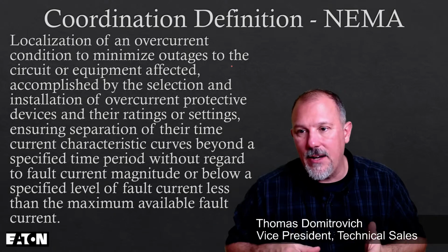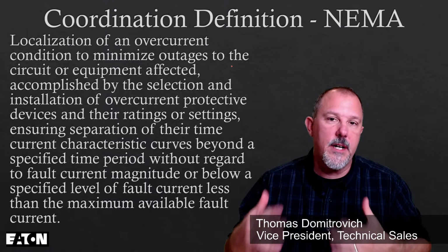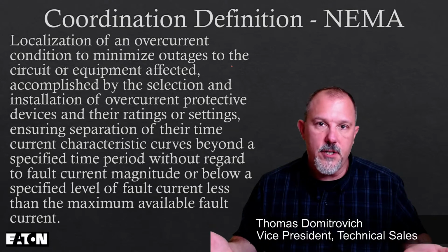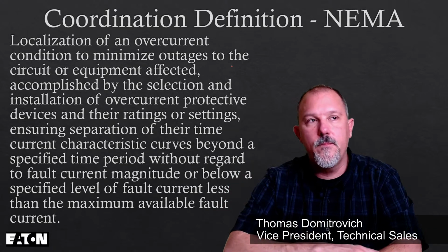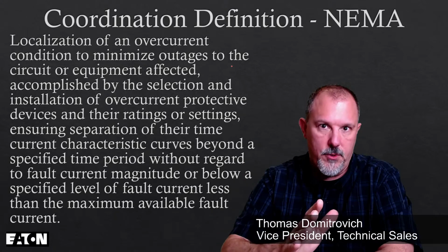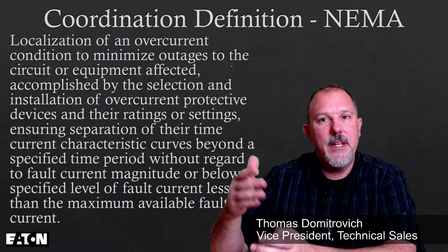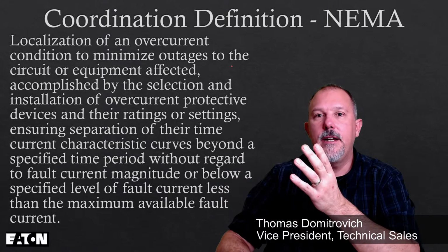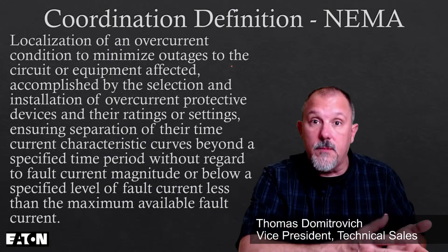And what that does, and now I'll tell you how I used that back in the day. When I would do this with customers that were in the commercial world, they would pay me to do a selective coordination study. I would plot the curves. When my bolted fault current was too high into the instantaneous range, I did not have the luxury of tables. Just put it that way. So when my fault current was higher than the instantaneous pickup of both overcurrent devices, I didn't have a code requirement that said I had to selectively coordinate. So it was a design decision. It was a customer decision.